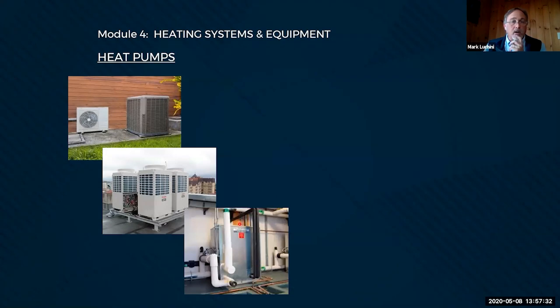It could also be water cooled rather than air cooled. In this instance, you see the refrigerant piping come in on the right side. It's transferring its energy to a pair of water pipes. Those water pipes could either go out to a well or to a ground source loop buried in the ground, or to a standard cooling tower. This is actually very similar to the system that is going in at Long Wharf.